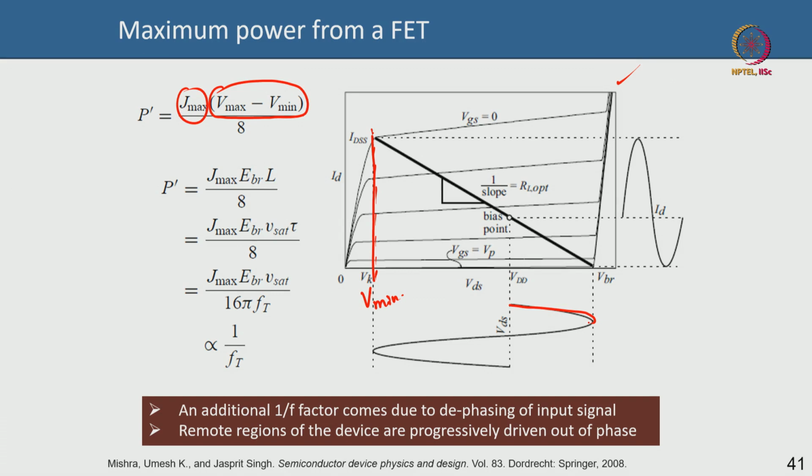In RF operation, when you bring the RF signal to the gate, at the output drain you are going to get a drain voltage swing like this, correct? So, this swing can happen between the breakdown voltage, which it cannot go above otherwise the device will break down, and the knee voltage, which it should not go below, otherwise the gain will significantly drop, because the linear region is of no use. Okay. You only use this saturation region, only there can you get the gain, and of course the output slope or conductance should be as low as possible.